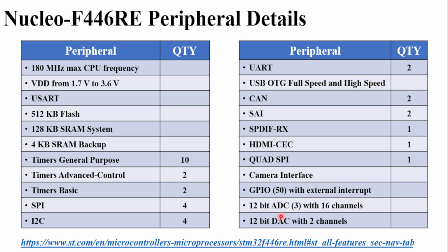We have 12-bit ADCs. So we have 3 12-bit ADCs available with the microcontroller board, which support 16 channels, and 12-bit DACs, digital to analog converters, mostly used for PWM purposes, and we can have 2 such channels with this particular microcontroller board. So for further details, you can visit this particular link to get all the details about this microcontroller board.